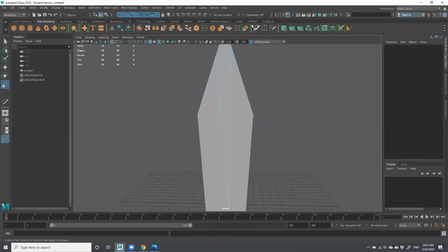Anyway, here what I would like to do is fix this geometry right here. I'm taking the multi-cut tool and clicking on this line. I get a little blue point, and I'm going to drag it all the way down until the corner. It'll stop, and then it'll become yellow. And I'll do the same on this corresponding side. It's blue, and if I drag it all the way to the corner, it's going to become yellow and stop.